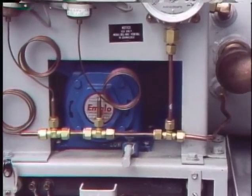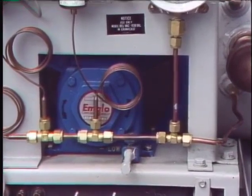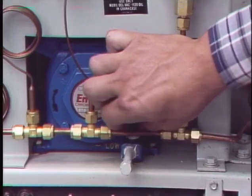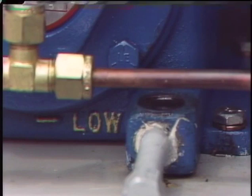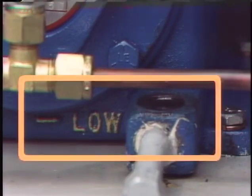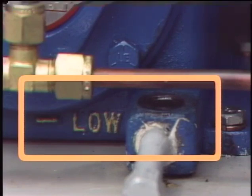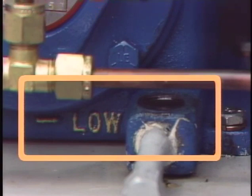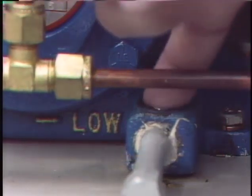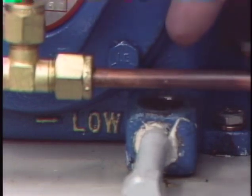Routine compressor maintenance generally includes checking the oil, air filter, and belt. The oil is checked in this compressor by removing an oil fill plug. A quick look in the fill hole will tell you if the oil level is okay. If the level is near the low mark on the crankcase, oil may need to be added. If the level is lower than that, you may need to look for leaks and fix them before adding oil. The condition of the oil can also be easily checked. If the oil is dark or gummy, it should probably be replaced.